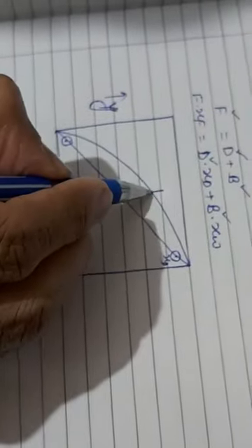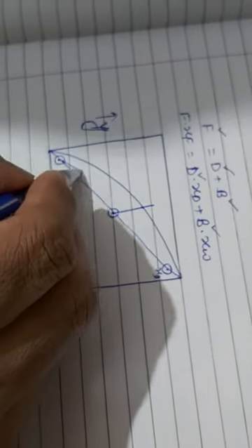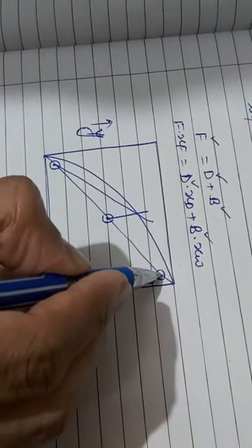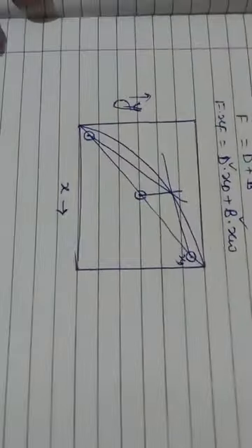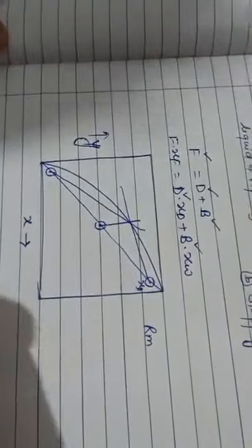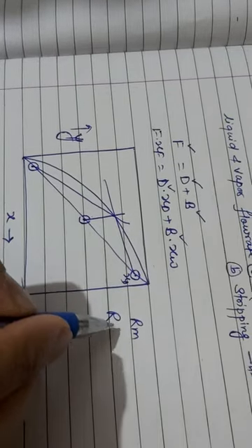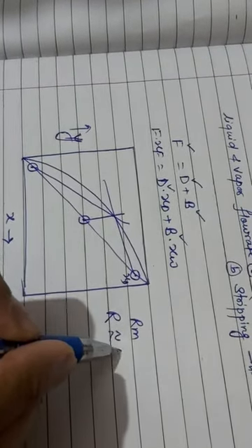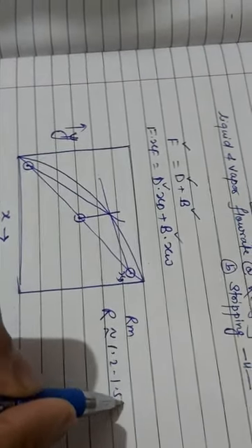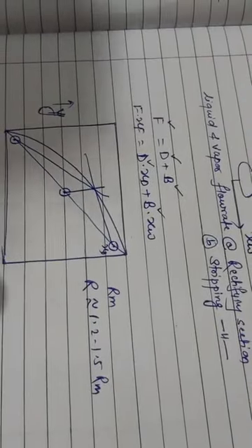Here you look at XD, distillate. This is for the bottom. And then wherever this meets the curve, you draw a line which will give us the minimum reflux ratio, RM, and we are aware the actual reflux is normally 1.2 to 1.5 times the minimum reflux ratio.